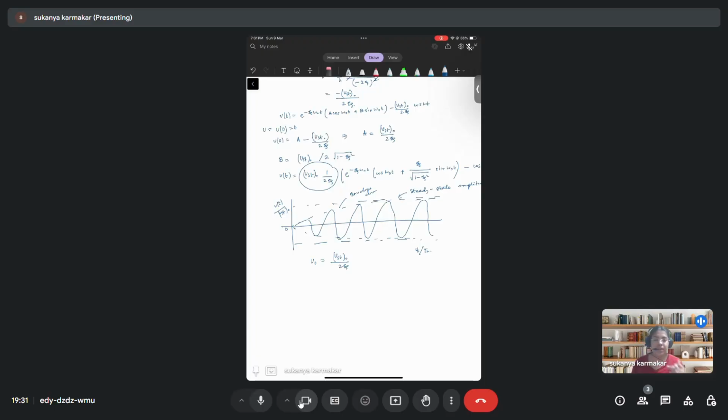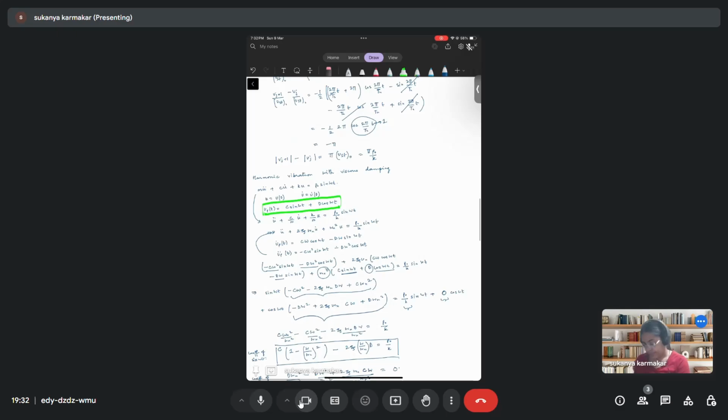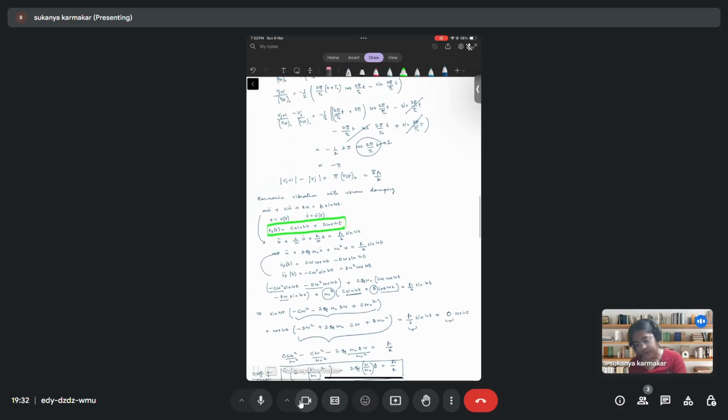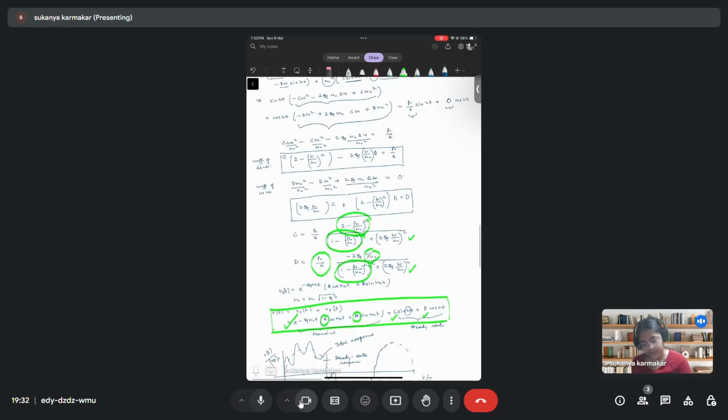Now we just studied the response reduction factor for undamped system. Similarly, we can study the response reduction factor for the damped system as well, where you will be using this equation. This equation which we just read, we took this equation and we calculated the equation for u.